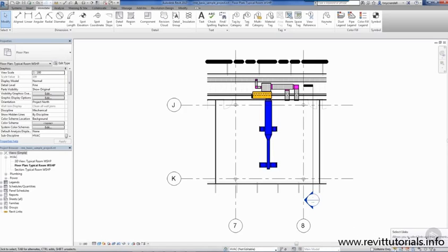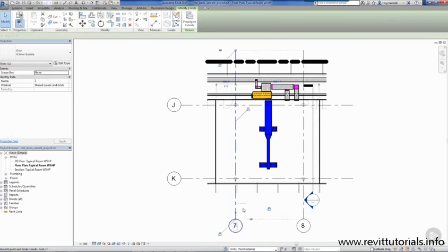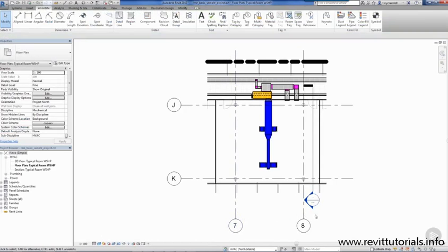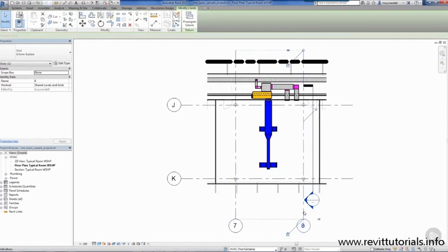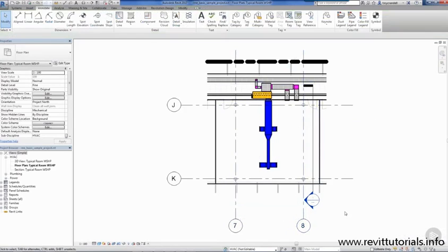Okay, these last icons here are filter selection. Now they prevent or allow selection of certain things in the view. For example, if I want to select pinned elements, well, I have to make sure this one doesn't have a red X over it. So there are a number of these, but the one that I make sure I have on is the last one.